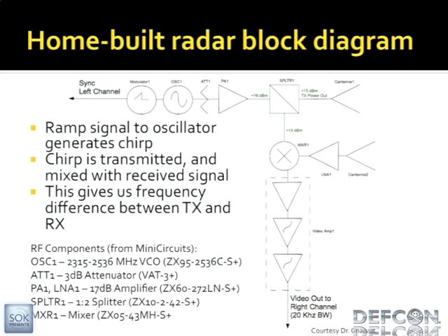So basically, what we did is we took the signal and we shifted it all the way down to pretty low frequency near DC where we could record it. And the original system for this used a sound card. I've actually changed that a little bit since then, but that's what's cool about this: you can literally build something like this and record your radar data with your sound card and just process it on the computer. You record with Audacity and then process it in MATLAB. That was how the original system worked.